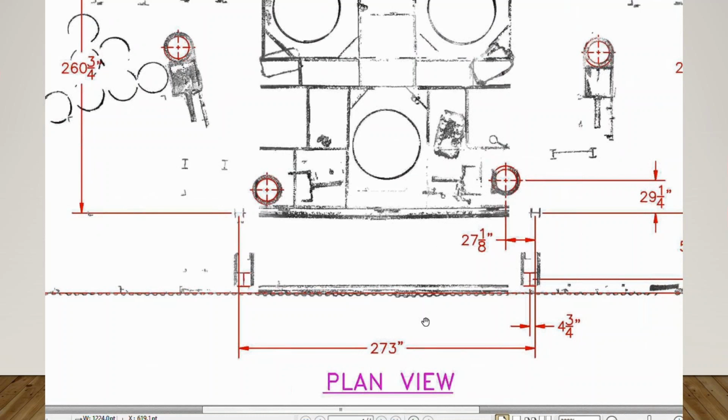Unless you're having that laser scanner work 80 or 90 days per year, it doesn't make sense to me to purchase one. I would rather rent the latest and greatest technology for $1,000 or less per day than have a scanner that gets old in 2 to 3 years.